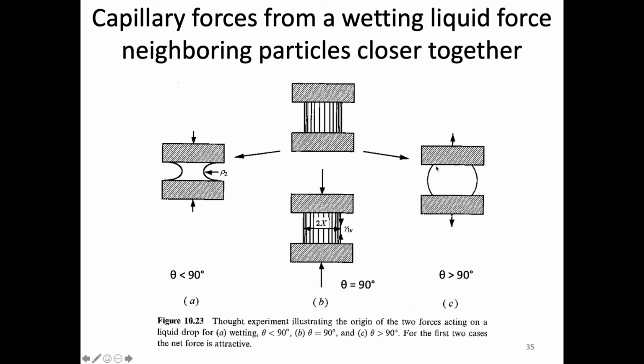And so in this case, now that we have two solid phases, we can see that it looks similar to the droplet. And so all of our liquid kind of beads up. And there's a natural tendency for that liquid to bead up and have less in contact with the solid. And so what that does is it pushes, if you're kind of thinking about the surface energies here, those surface energies balance out such that there's a force acting to push the solid plates away from each other. So the force is basically to push the solid particles further apart so that this droplet can kind of consolidate into one sphere.